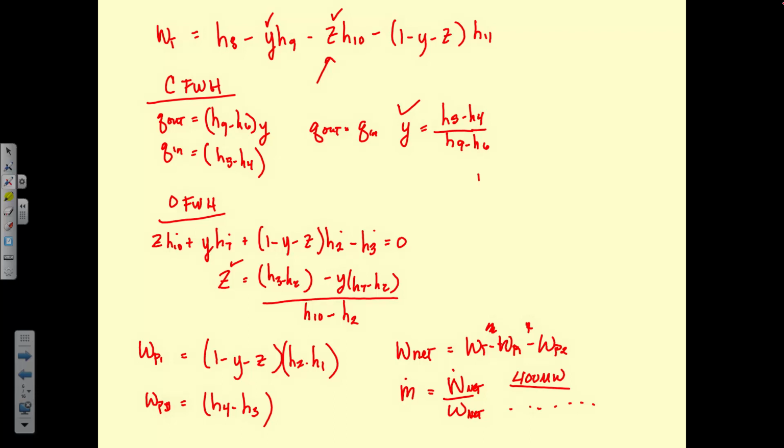Okay, so then for part B, the thermal efficiency of the cycle. What is the thermal efficiency of the cycle? What's the equation for it? It is equal to work net over Q in. So we already solved for this work net. Q in is equal to what? Where do we have a Q in? Just the closed feed water heater and boiler.